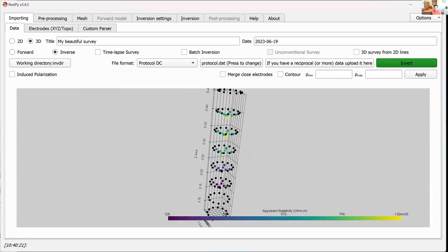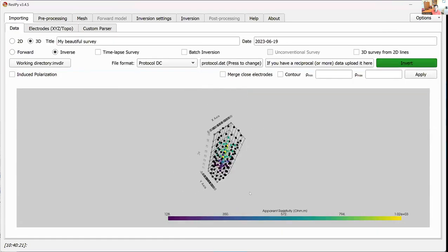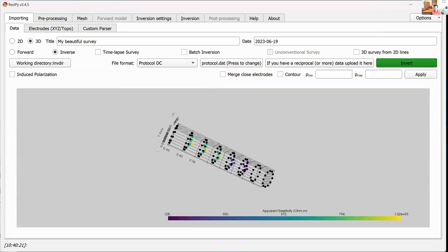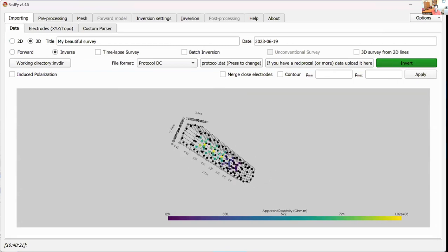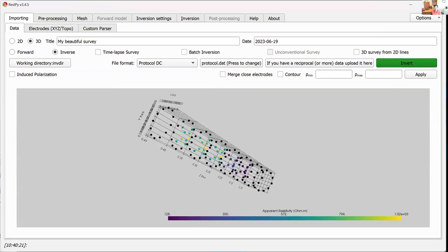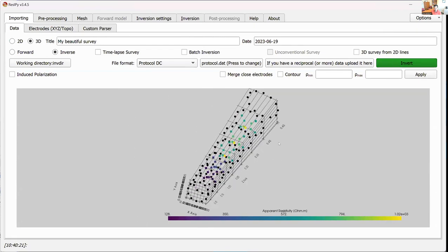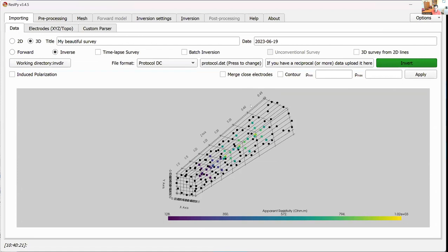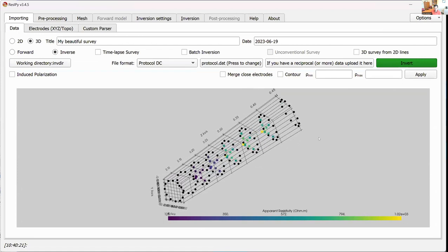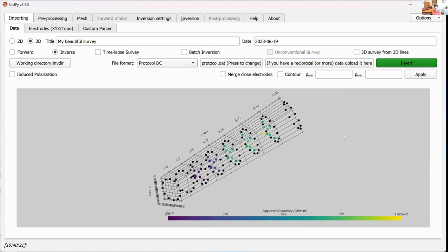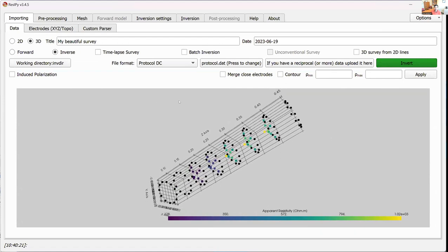Go back there, you can clearly see this looks like a column experiment, right? So a couple of things in here that are really important that you may want to note when you're creating a column. ResIPy by default will try its best to define the bounds of this box around your cylinder, but it might be difficult for it to correctly define the bounds. And if you incorrectly define the bounds during the meshing, the mesh will not be defined correctly.